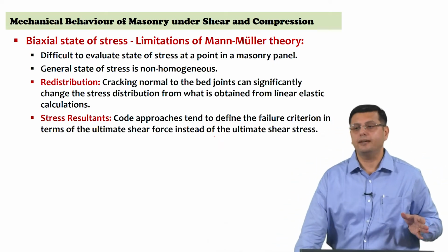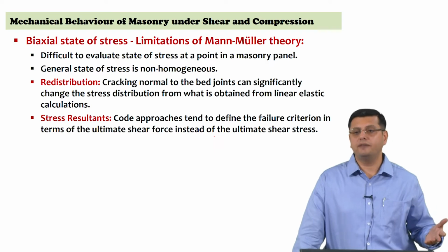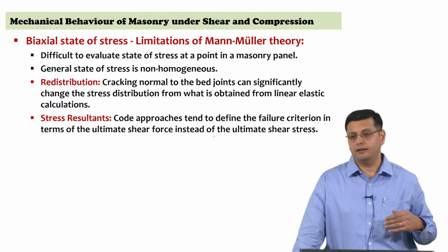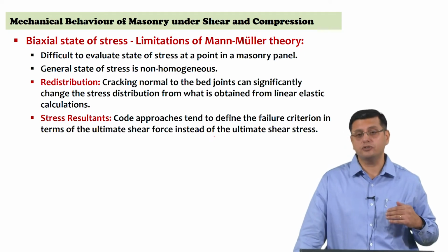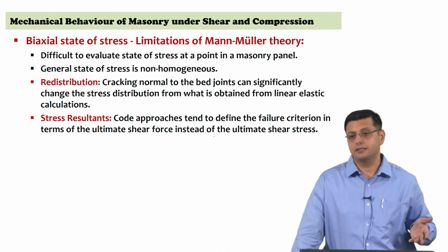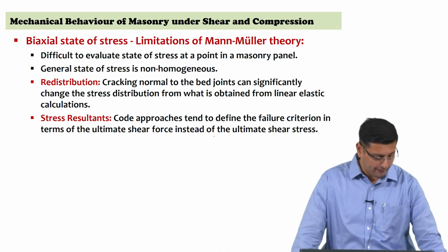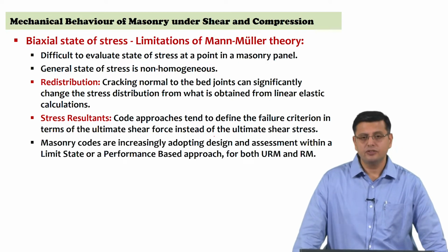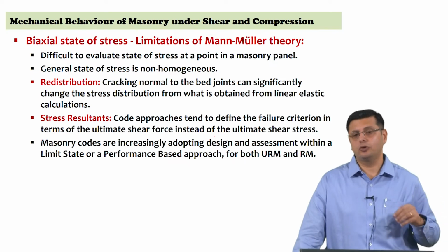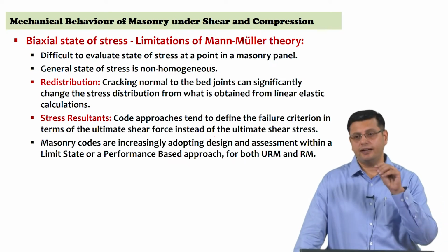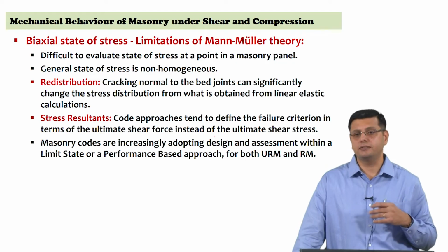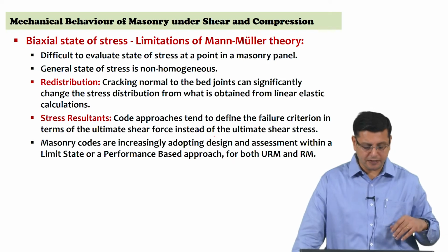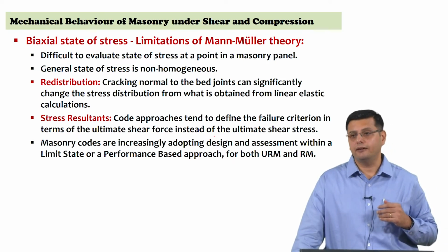And the other important aspect is, if you look at the way codes define design procedures, it is not at the state of stresses that we work. It will be easier for us to work on stress resultants, and therefore, it is useful to have these expressions extended to stress resultants if possible. So, if you are looking at a limit state approach, or a performance based approach, and if limit states can be designed both for unreinforced masonry and reinforced masonry, this then becomes an interesting set of expressions that you could use to define the interaction.